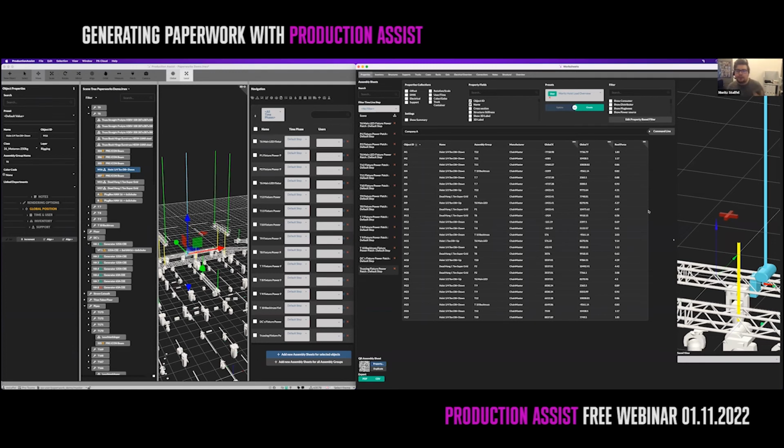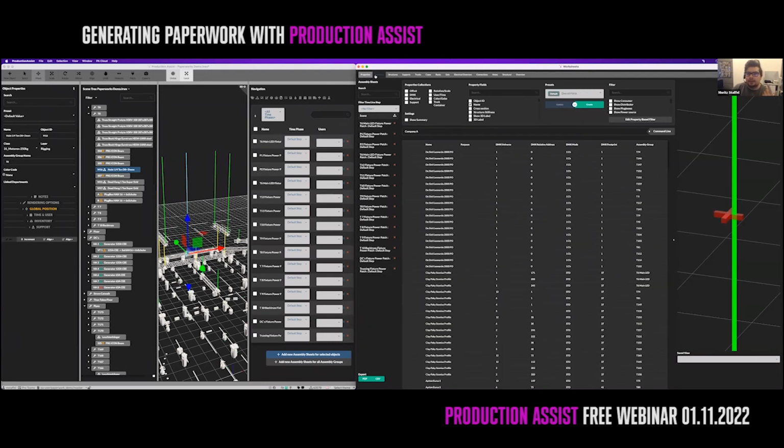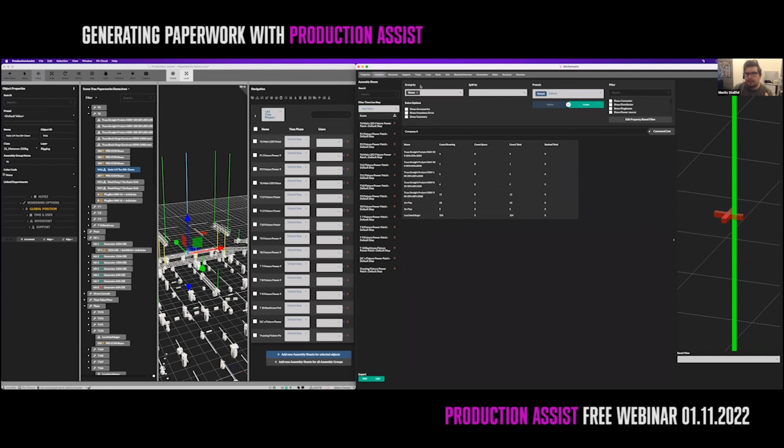Okay, then let's have a look at inventory. A common thing you need for sure is inventory. You need to know how much is in there. In order to get this, we're going back to the scene objects, so all the objects that are in here, and then I'm going to the tab inventory. The tab inventory lists me now all the objects that are inside my drawing which are matching my specific filter, which I assigned. Right now, I have the filter set to show structures, which will basically only show me the structures in here.